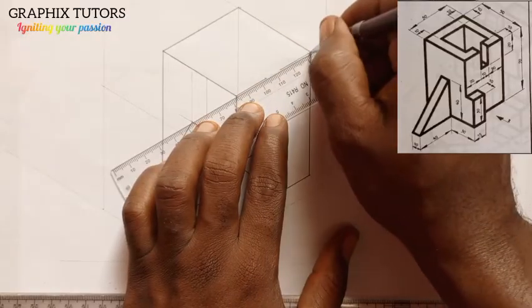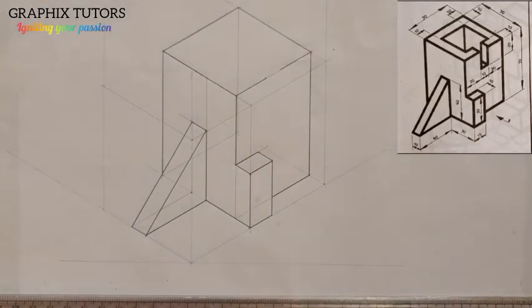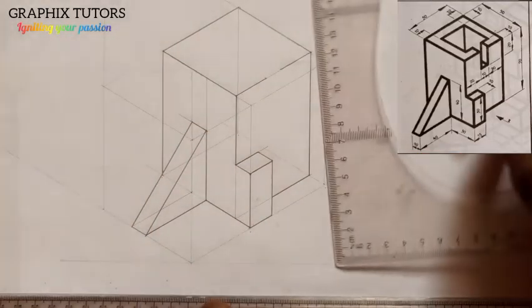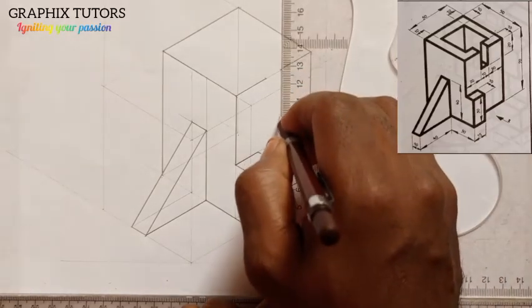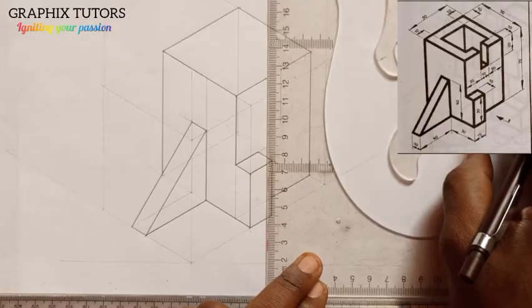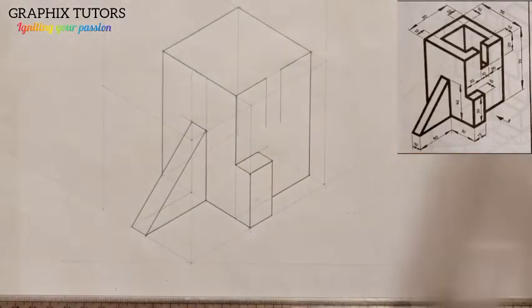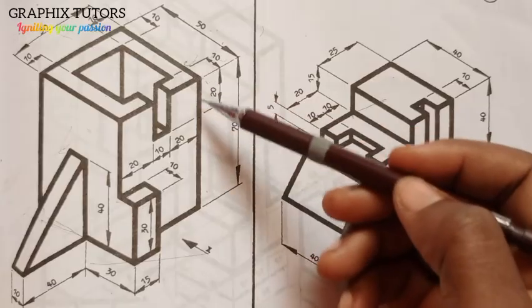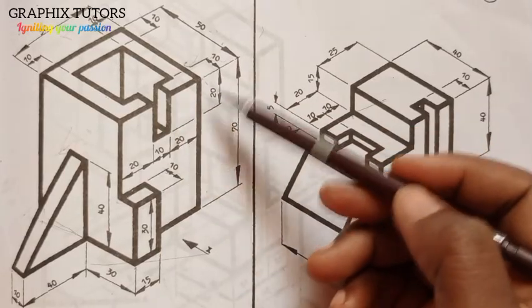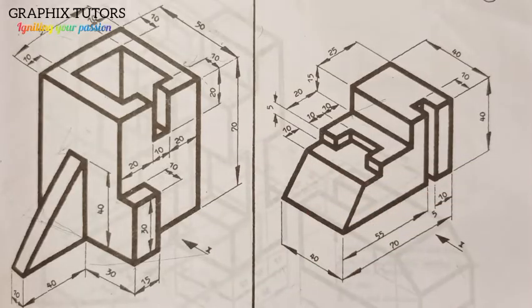This is what we have. And I'll bring it down with my set square and t-square. Faint line first of all. And here also faint line first of all. So what is the depth of that? So let's look at it. So the depth of that from here to here, if you look at the line, it's given us 20. So I measure 20 down.